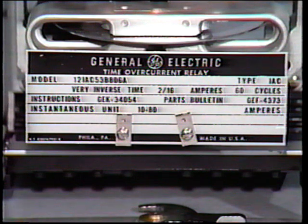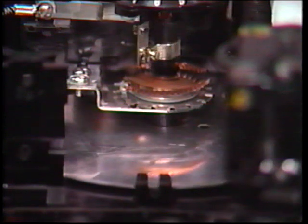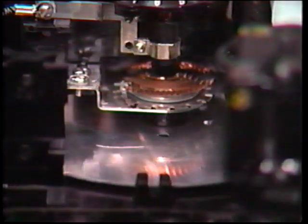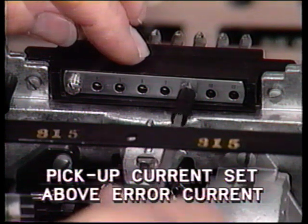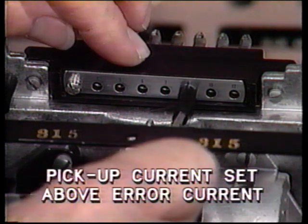The most simple is to use the delay of the time overcurrent relay to ride through the transient period. A time delay of about 0.2 seconds, that is 12 cycles, is sufficient on most applications. But this may have to be increased if the bus is located close to a generator. The pickup current should be set so that it's above the estimated error current generated by the CTs for the through fault. This system is quite economical and is often used on low voltage buses, but you can see that it's slow and not very precise.